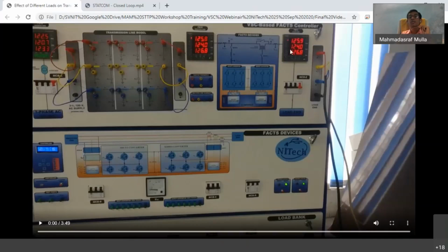Reactive power is a 90-degree phase shifted voltage and current, so the average value of that waveform is 0. That is how, without any source, it can be supplied. Capacitor and inductor can exchange energy with each other and infinitely keep exchanging the energy. So we don't require any source. The capacitor will give, the inductor will store; the inductor will give, the capacitor will store. That way reactive energy exchange can happen between lagging current and leading current.